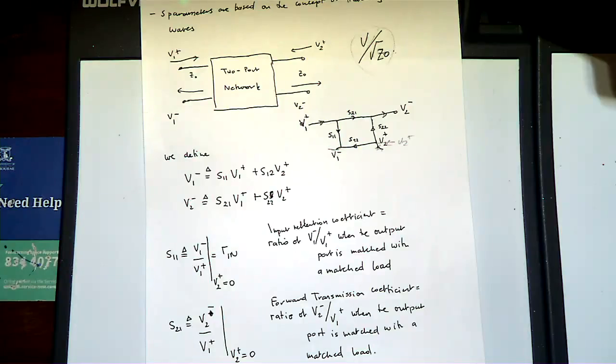Correct? Yes? When it's measuring S11, what's it doing? Did they draw you a diagram of what a vector network analyzer is actually doing? I'm sure they did, or they explained what was happening, right? So essentially the vector network analyzer was putting a signal of certain current and voltage into one port, and on the other port it was switching in the 50 ohm load.